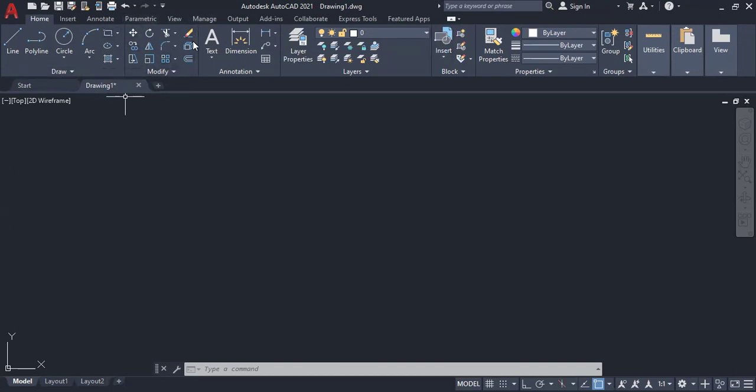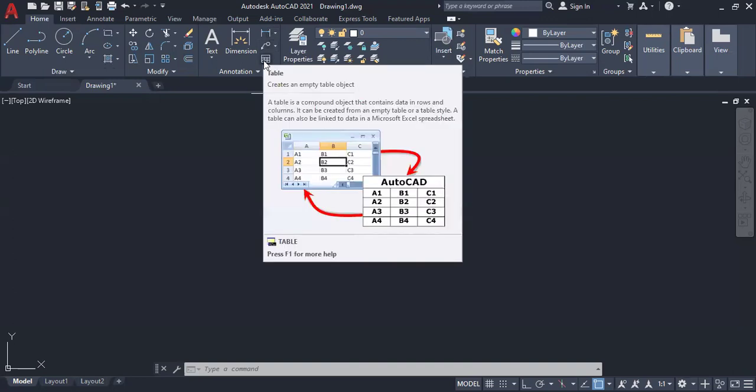And then modify commands. If you want to modify anything of your geometry or your sketch, there you can do move, rotate, trim, offset, mirror, scaling, array, these kinds of things. The next one is annotation. In the annotation, you can write text in your drawing, whichever description you want. Then dimensioning, after which you'll have leader and linear dimensioning. And if you want to prepare a BOM or something, you can directly import complete tables from an Excel sheet into AutoCAD. This is one thing.